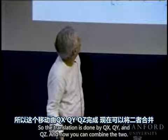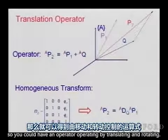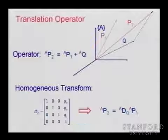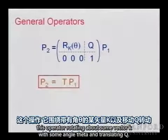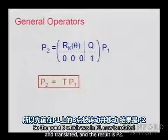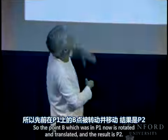And now you can combine the two. You can combine the rotation and translation, so you could have an operator operating by translating and rotating. So the general operator that you can imagine is this operator rotating about some vector k with some angle theta and translating by q. So the point P, which was in P1, now is rotated and translated. And the result is P2.